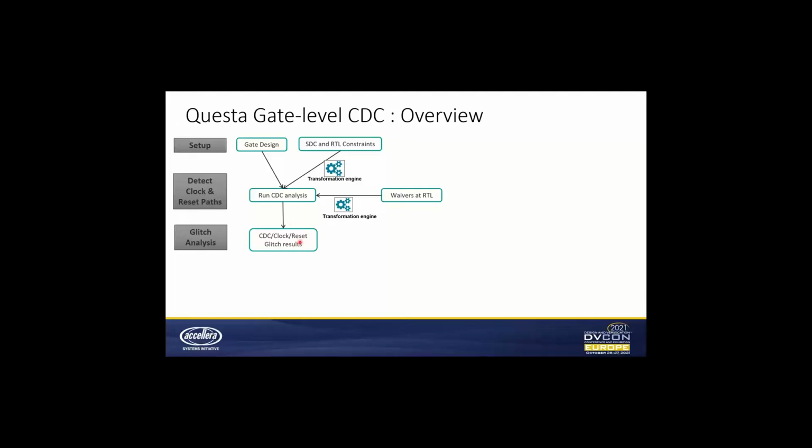We do the expression-based analysis, which identifies the combinational logic that may contain the glitch. Now the next step is to perform the gate level formal analysis on that combinational logic to identify whether the glitch actually propagates to the receiving logic or not. So the glitch list is further pruned to identify the scenarios under which the glitch really propagates. For this, we utilize the formal engines to verify the glitch propagation conditions and conclusively give counterexamples for that.